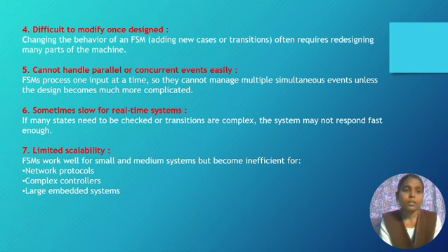And next one, fourth one, difficulty to modify once designed, changing the behavior of an FSM. That means adding new cases or transitions often requires redesigning many parts of the machine. Fifth one, cannot handle parallel or concurrent events easily. FSMs process one input at a time, so they cannot manage multiple simultaneous events unless the design becomes much more complicated.